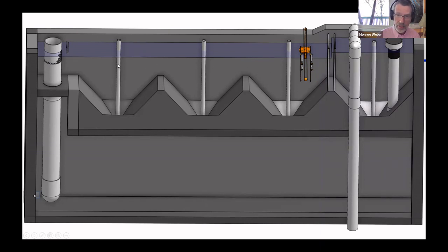This long section of the entrance tank is about providing an opportunity for pretty high density particles, grit, think small sand, to settle out so that it doesn't end up clogging our flocculator. So things that would have settled out anyway in the plant, you want to catch them here so they don't settle out and give you a maintenance issue later on in the plant.